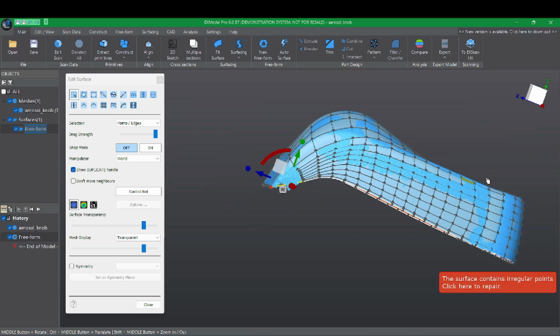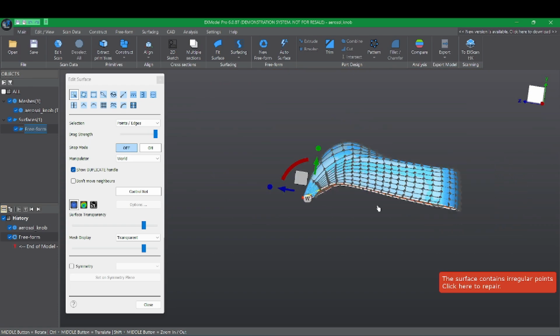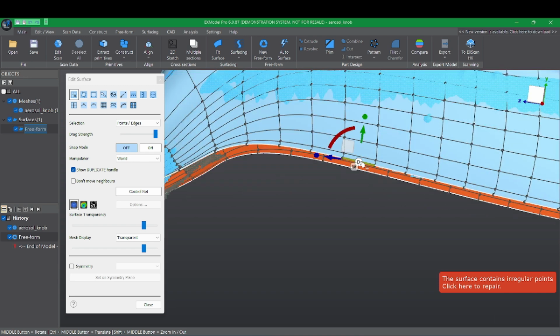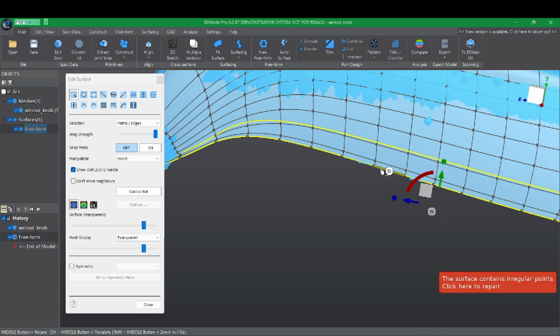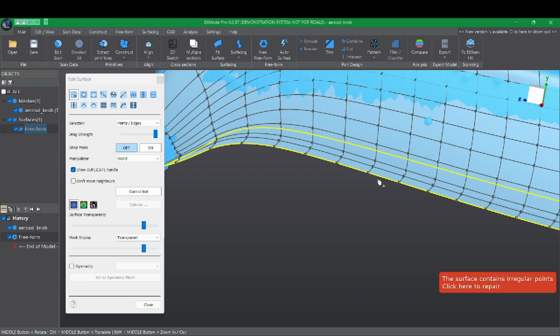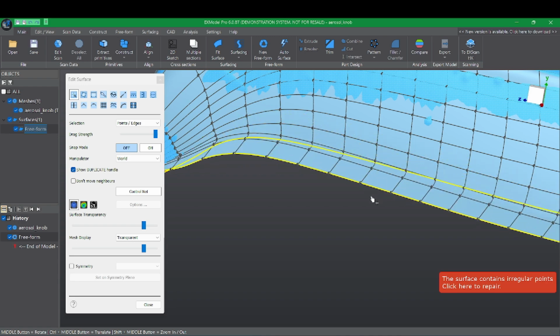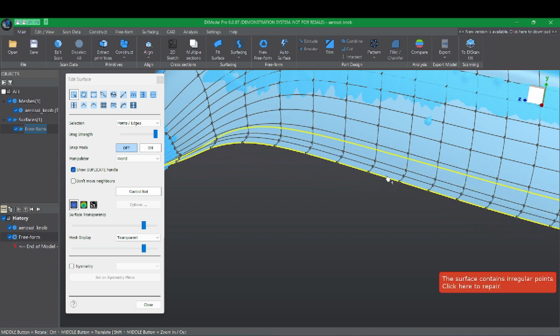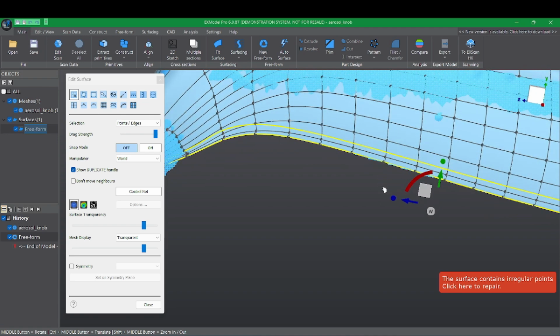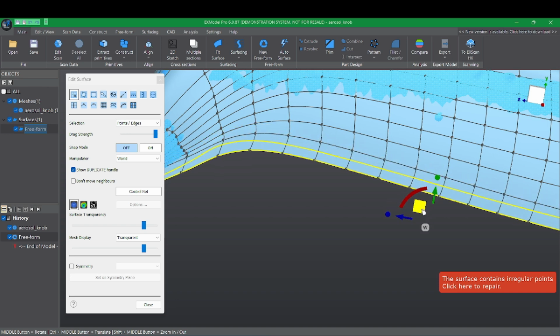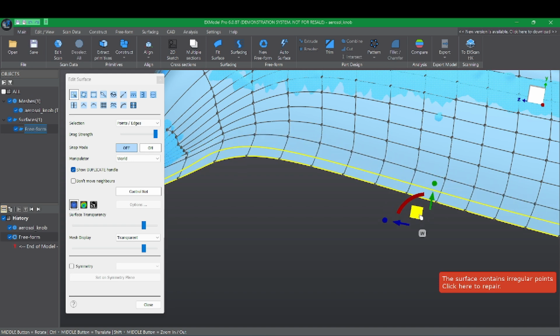One other option of the extending, in this view, is when we duplicate, it will just duplicate in this direction. But if I hold Control and Alt key, the duplication will be actually extending the surface, which means that the new point will go in this direction, the other one in this direction, and this point will be duplicated and moves in this direction. So hold Control and Alt key and start duplicating.